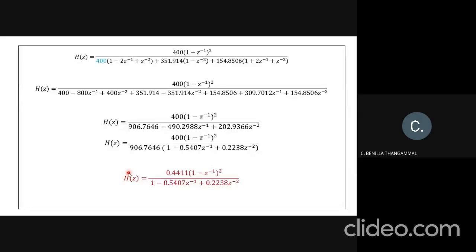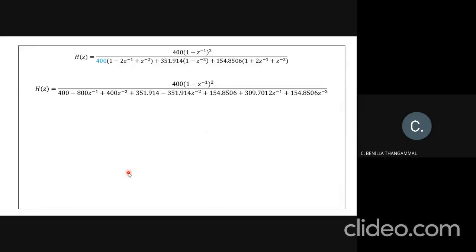Right, so these are the varieties of problem that can be asked. So in your analog design procedure, first you find the order of the filter, next find your omega c, then find the normalized transfer function, and step 4, find your unnormalized transfer function that will give you your H. This part you have to stop. So after obtaining this part, I have to stop.